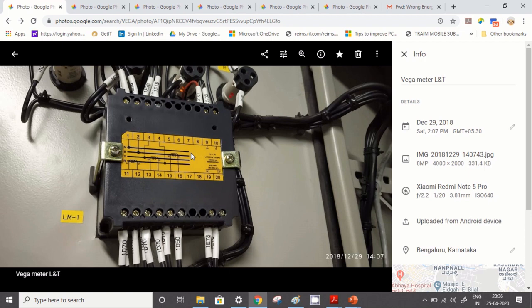Sometimes it happens that a meter is showing correctly on its display, but even after a proper connection you are not getting values in your portal. At that time you have to check all the connections properly, because the connection could be loose, or the port itself could be faulty. If the port is faulty, you cannot do anything here, you have to replace the entire meter. So now let us go to the parameter setting section, in which we will discuss the parameter values.